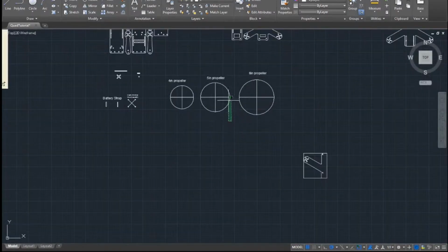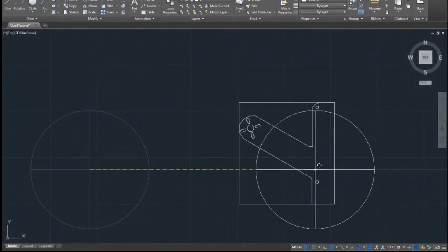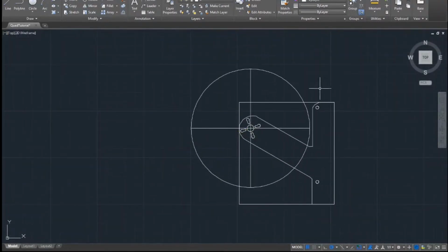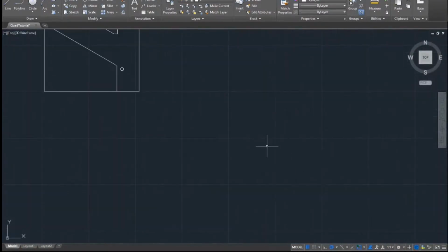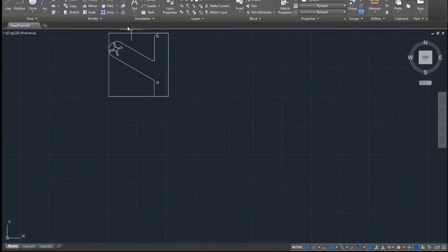Now, also before we copy this over, we want to make sure that our desired propeller fits. So for a 250, we want a 5-inch propeller. Just drag this over and plop it right there, and then you'll see we got enough clearance so that we won't get any aerodynamic harmonization or clipping of the frame. So that we're good with that.